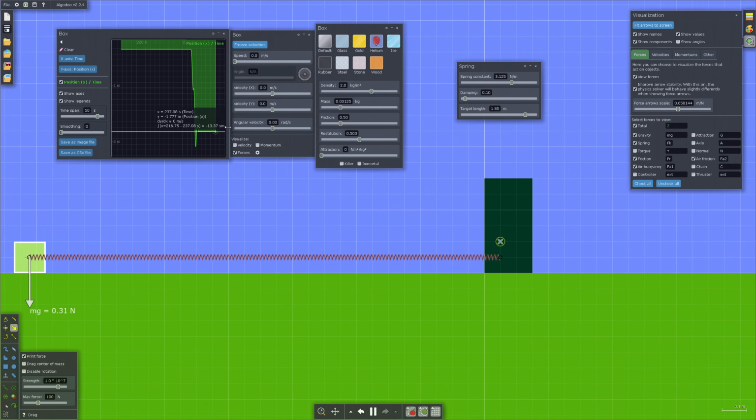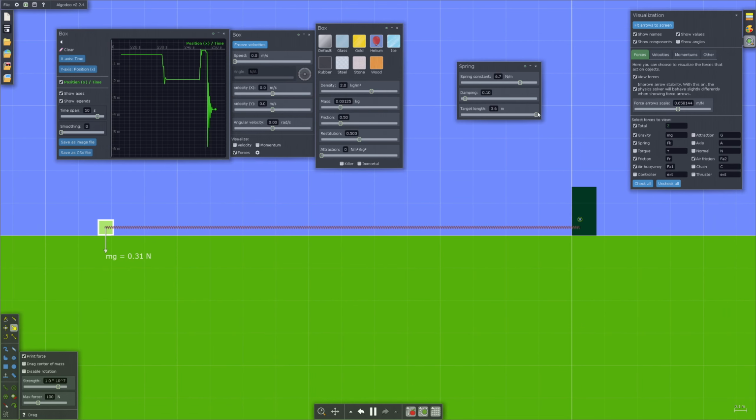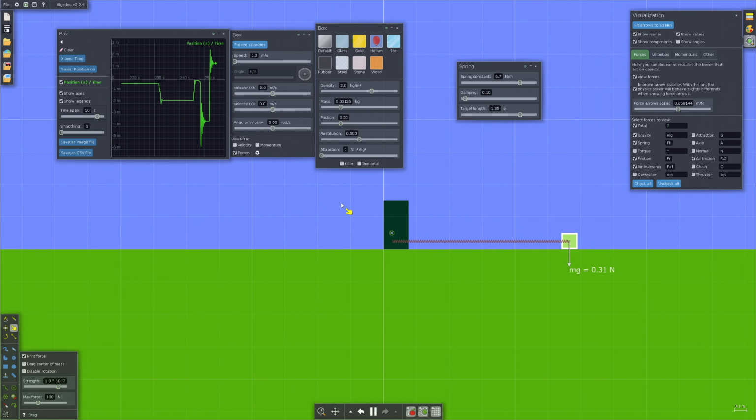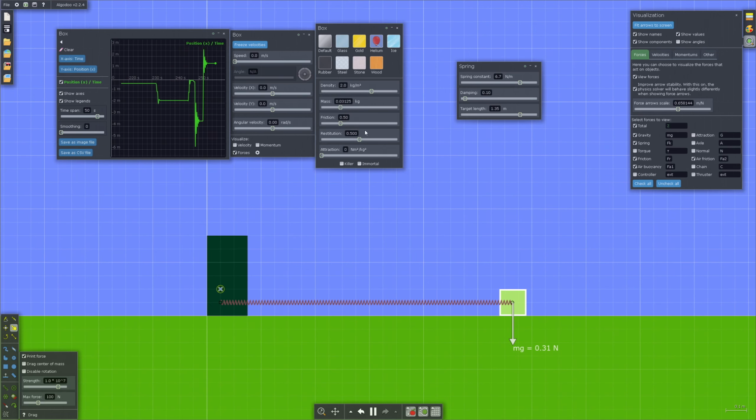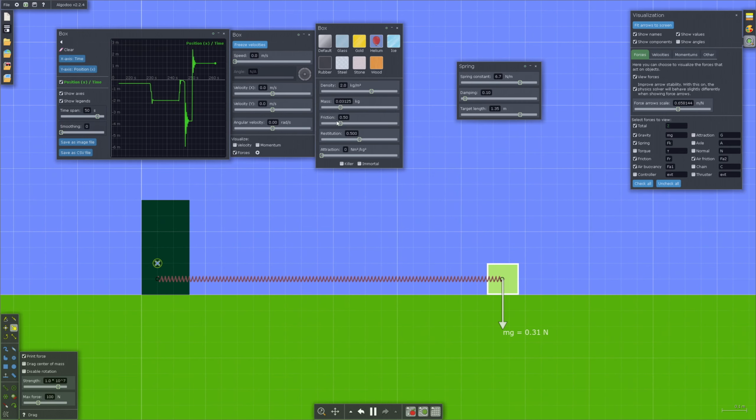Now, as you can see, nothing has happened because the friction was actually too high. So you can reduce it, and let's see. Yeah, as you can totally see, we have to reduce a little bit the damping to make the same simulation as LTspice. So the friction now is set to the minimum. You cannot set it to 0 because if you set it to 0, it will start to vibrate. So let's set it to 0.1 and the damping also to 0.1. Now, let's pull the spring.